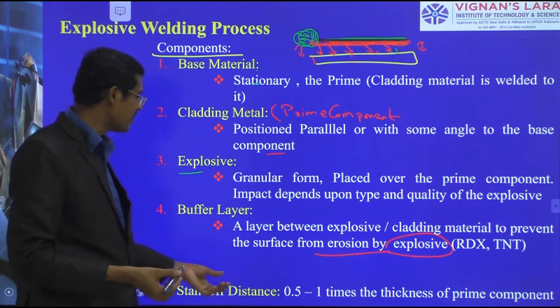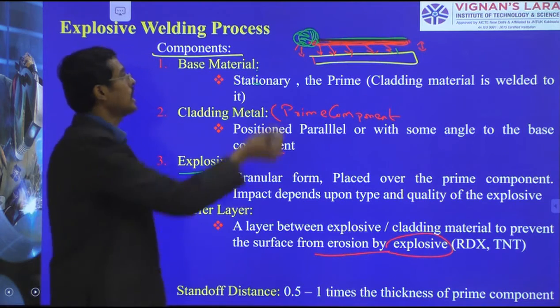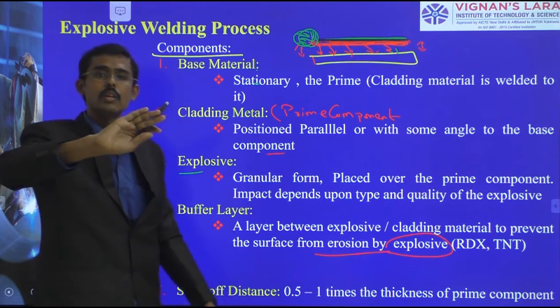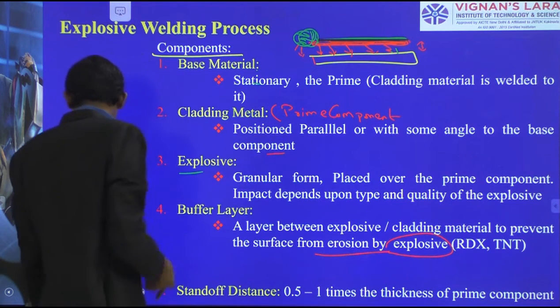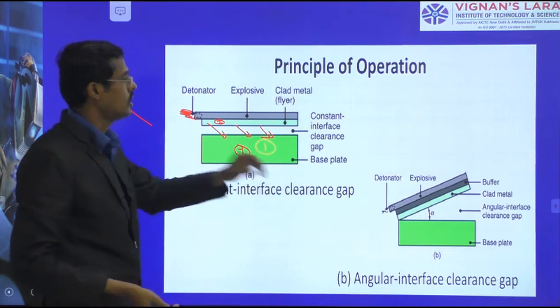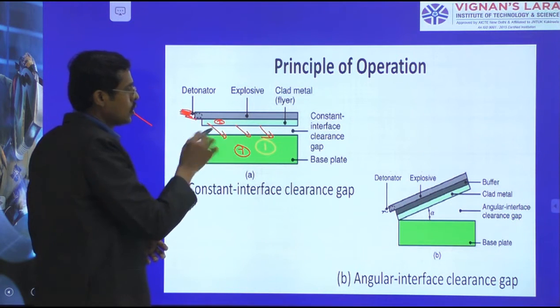The standoff distance may be 0.5 to 1 times the thickness of the prime component. So the standoff distance is how much parallel gap we can keep, matching the thickness. This is what I have delivered now. We have kept two specimens parallel.